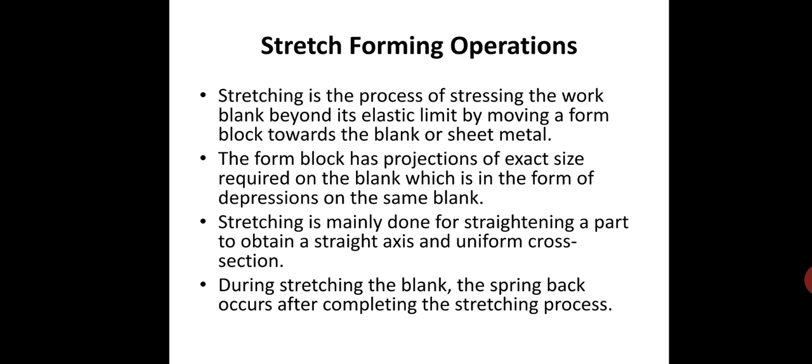The form block has projections of extra size required on the blank, which is in the form of depression on the same blank. Stretching is mainly done for straightening a part to obtain a straight axis and uniform cross section. During stretching, spring back occurs after completing the process.